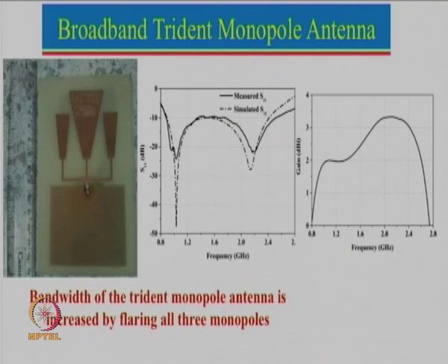So we actually got a little carried away, and decided why not make a broadband antenna right from the low frequency to the end frequency. Now in order to realize a broadband antenna, instead of using a simple monopole antenna, we have used a triangular monopole antenna, and even for the side patches we use a slightly tapered antenna so that we can get a broad bandwidth. So this gave a little more bandwidth, and this one also gave a little broader bandwidth. One can now see that the response is right from here to here, with reflection coefficient less than -10 dB over the entire band.